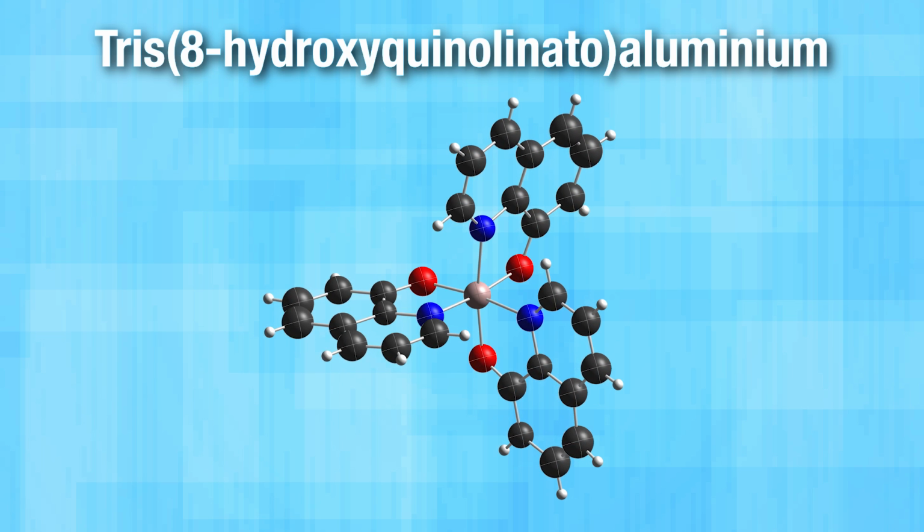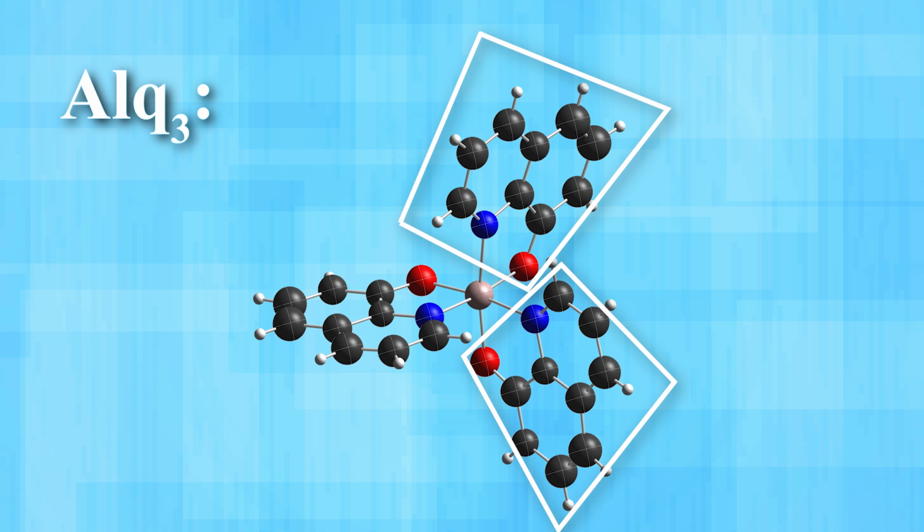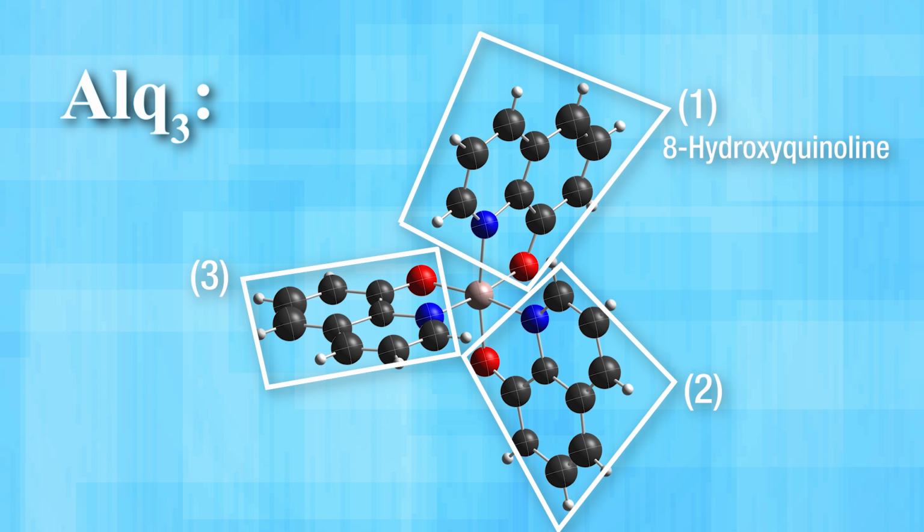One example of a small molecule used in OLED is, well, this name, abbreviated as ALQ3. This molecule contains aluminum and carbon and is known as an organometallic chelate. That's not really important, but it just sounds cool. Here, the aluminum is in the middle, and it's surrounded by three branches of a group of molecules known as 8-hydroxyquinoline. According to a 2006 scientific paper, this organic compound is special because by modifying and substituting certain atoms in it, you can tune the frequency of light emitted, so it can be used to create various colors spanning the entire visible spectrum. In simpler terms, you can use it to make lots of different colored pixels. That is just one example of a molecule used in some OLED though. There are lots of other potential small molecules.